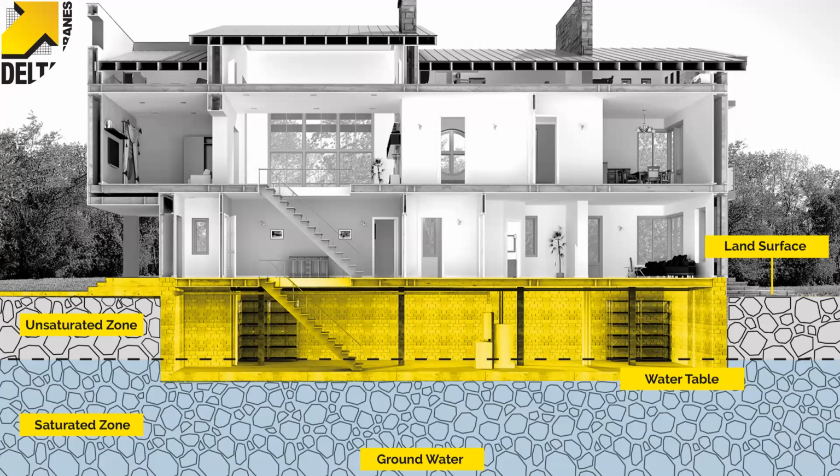Water tables, okay. So in BS 8102, it says, is the water table low? Is it high? Is it variable? Well, sometimes you just don't know, okay, especially if it's an existing building, because we don't always have site investigations and trial holes and geotechnical reports. But the fact of the matter is, whether it's low, high or variable is almost immaterial, because water tables change. Okay, they're higher in winter normally, they're lower in summer. If you build an office block next to the building, that could displace water in the ground, create an artificially high water table where there wasn't one before.